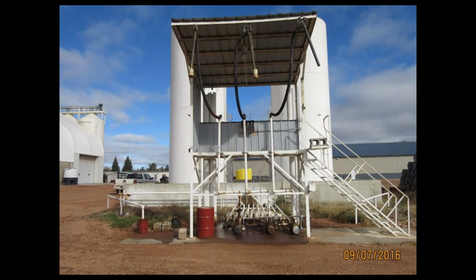This is another hint. Whether you own the facility or you're a locality or tribe looking at it, transfer areas are a very high risk area for spills or discharges. In this case, the facility has what we call a manifold that takes the oil from the trucks to the facility, as well as the top loading devices you see. This is where the transfers are. Something is leaking in that manifold. Now, if that's a flammable liquid, that's a big problem.